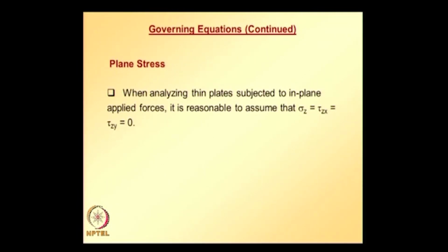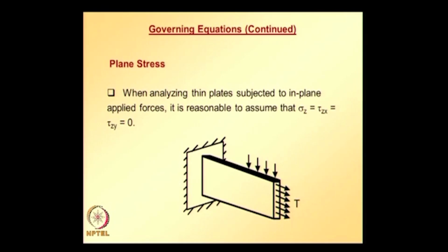When analyzing thin plates subjected to in plane forces, it is reasonable to assume the out of plane stress components are 0, like sigma z, tau x z, and tau z x is going to be same as tau x z, and tau z y, all these 3 are equal.